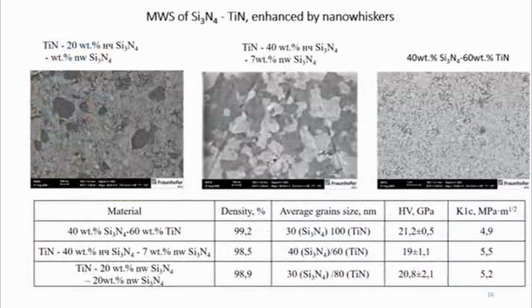Microwave heating is a non-conventional sintering technique to solve the difficulties found in previous techniques such as spark plasma sintering. The microwave technology was specifically designed to fabricate ceramic bodies with a high density, very low secondary phase proportion, and high mechanical properties. An important characteristic associated with the microwave process is that it is possible to directly obtain material with a complex part, near net-shaped components, directly in the microwave furnace without the application of pressure and without any carbon contaminator.